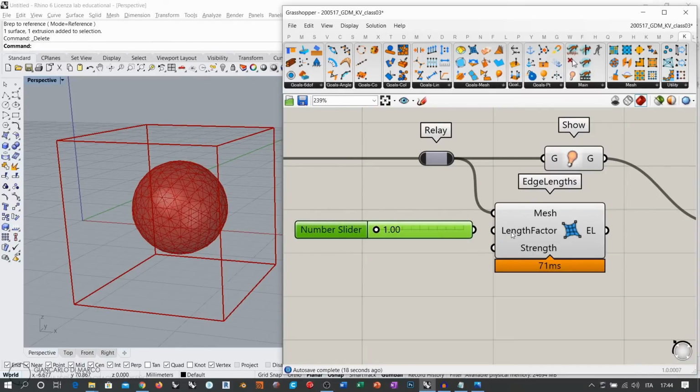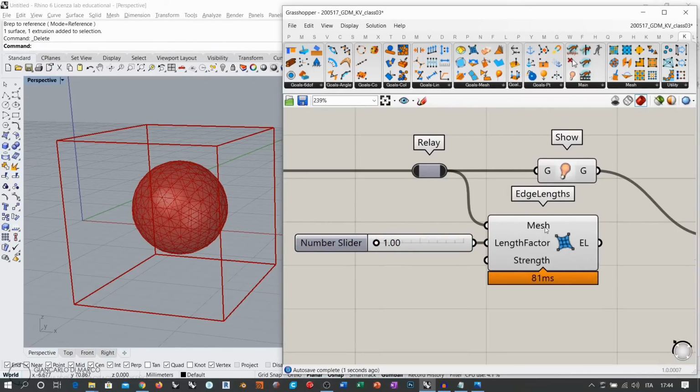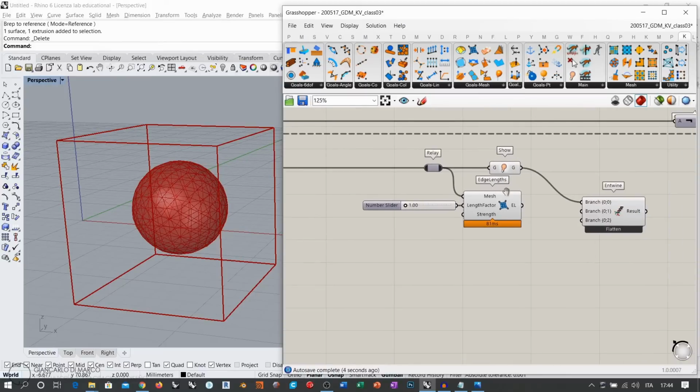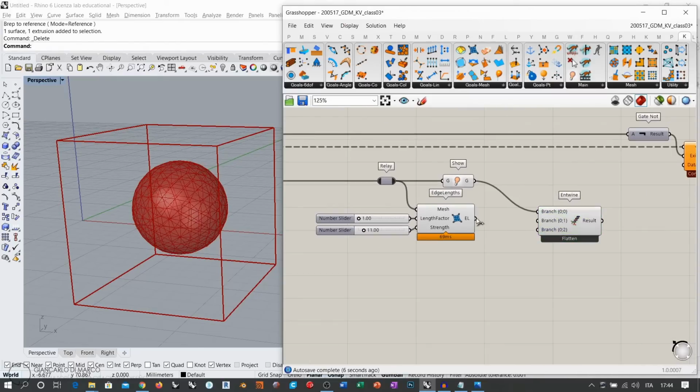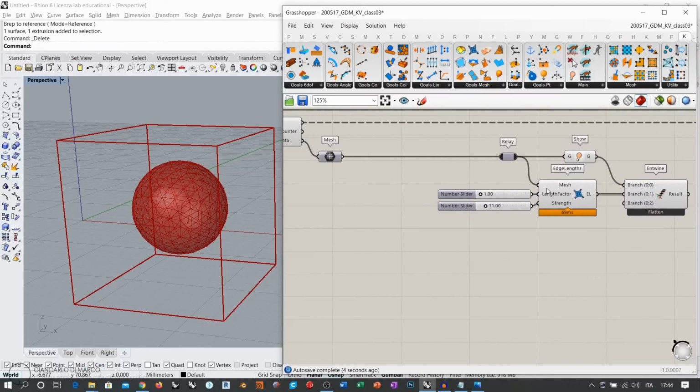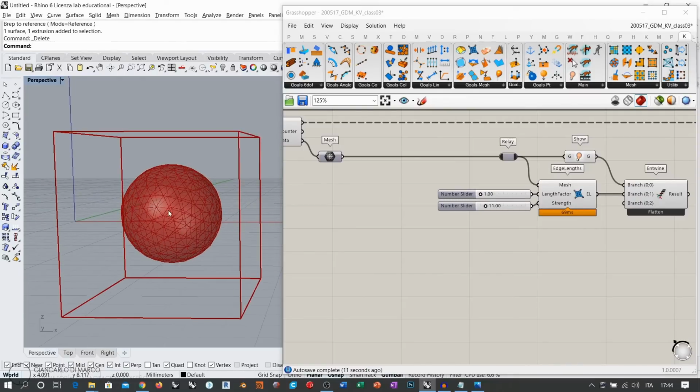Length factor 1 means that the mesh is not going to expand by itself unless we apply some other force, as we are going to do right now. And also we want to set here a variable, maybe I exaggerated with the amount of decimals, a variable strength, so we can actually define if this elastic property is more or less strong. And so we have the elastic property already set up. And then we want to inflate this thing, or have some action that makes this object expand.